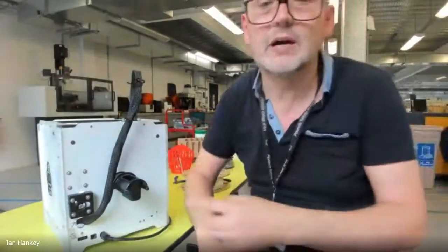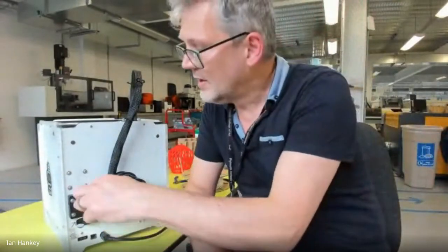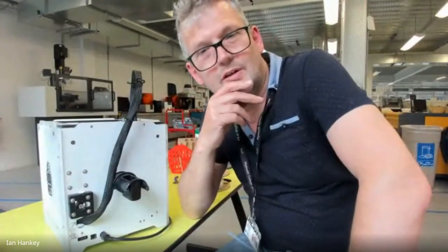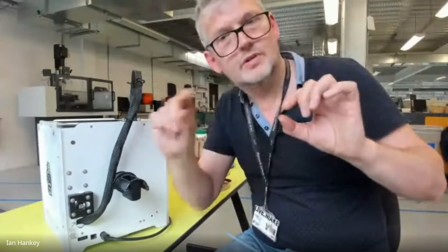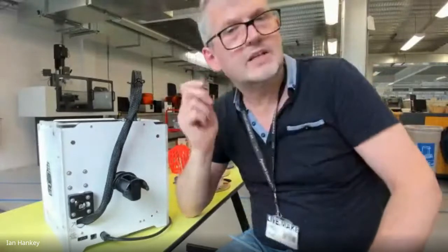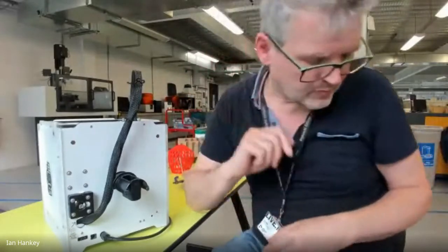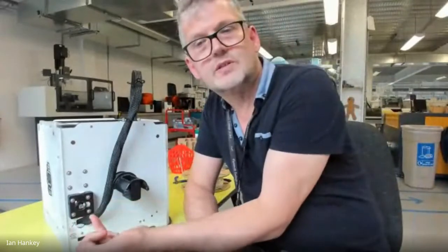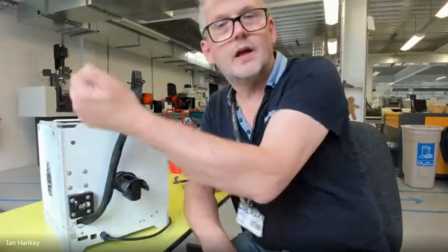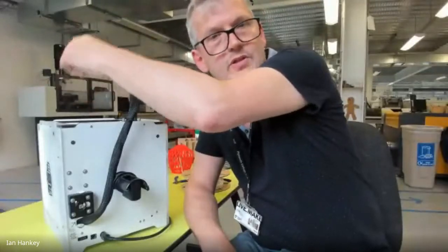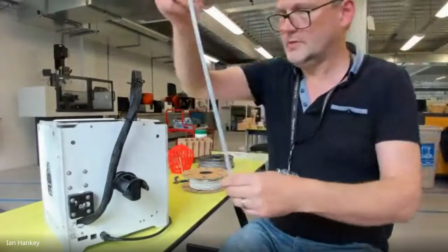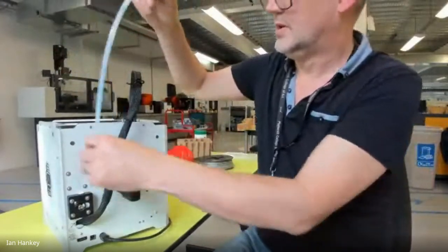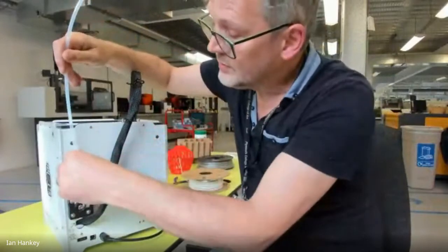Okay, the first thing I'm going to point out is this bit here. There's a motor here. And remember when we pressed slice on Cura, it not only took our model and sliced it completely, but it wrote G-code. And that code gave instructions to each of the motors on this machine. And one of those motors is the motor that brings the filament up and over and into the hot end so it could start printing, just like a glue gun, as I mentioned. So what I need to do is fit this tube now onto the top of the motor.